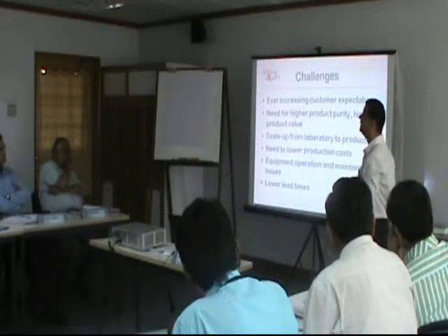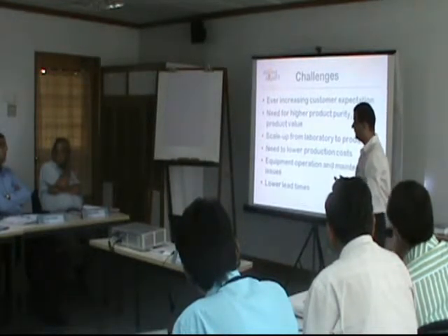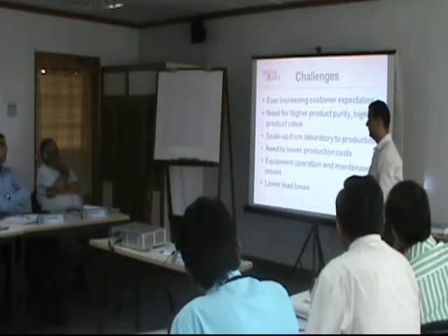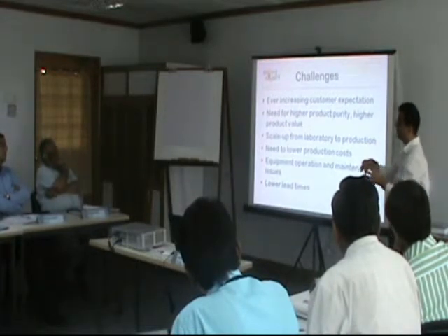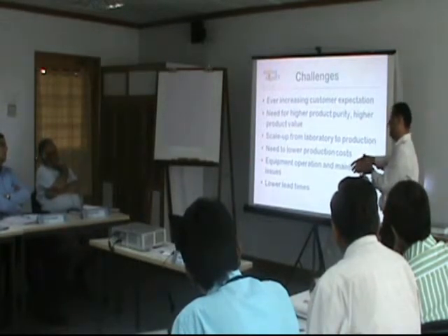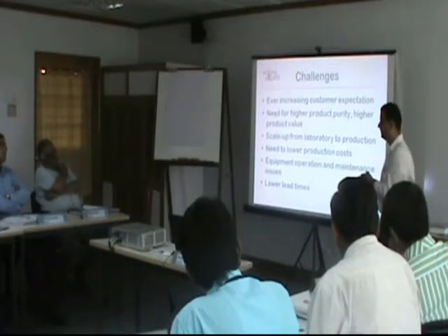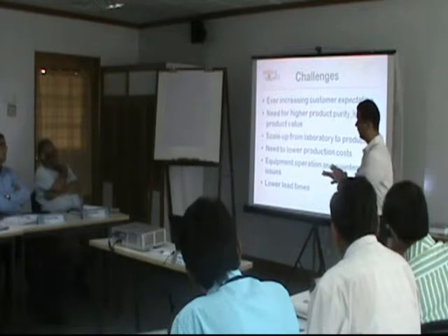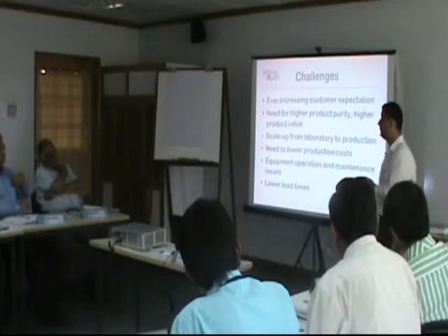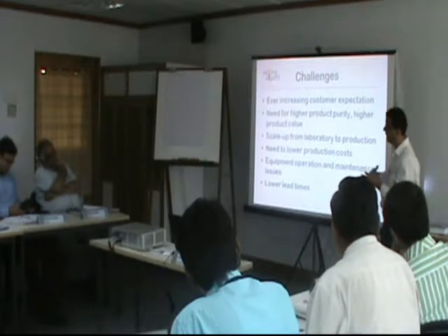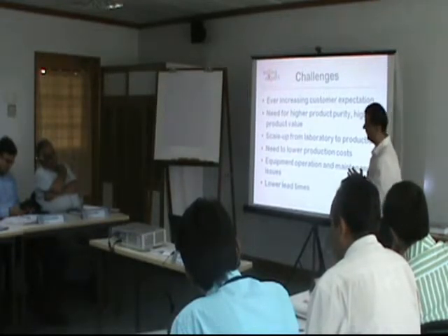The second thing is, how do you prevent segregation? A lot of times, if the material is overmixed, it will begin to segregate. That does happen. An example which comes to my mind is salt and pepper, which will never mix. They will always remain in a segregated state, and you cannot do anything about it. But there are certain materials which, over a period of time, will have a tendency to segregate. In those cases, at the plant level, they always keep those materials, even after mixing, under some kind of gentle stirring.